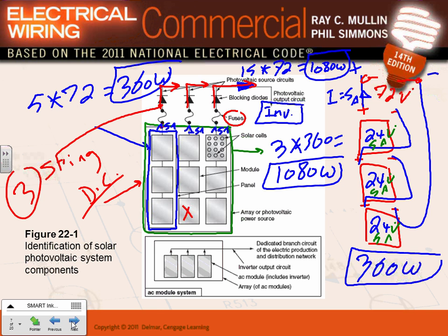This system here is called the DC system. This system here is the AC system. The only difference, Jeff, is they have the inverter as part of the panel. The inverter is right in here. They put the inverter right here, and they actually tie together AC circuits in sync. So string 1, string 2, string 3, instead of being DC, these are AC. The time you get AC is right here. AC is converted right at this point. This is where you get your 240/120 volt.